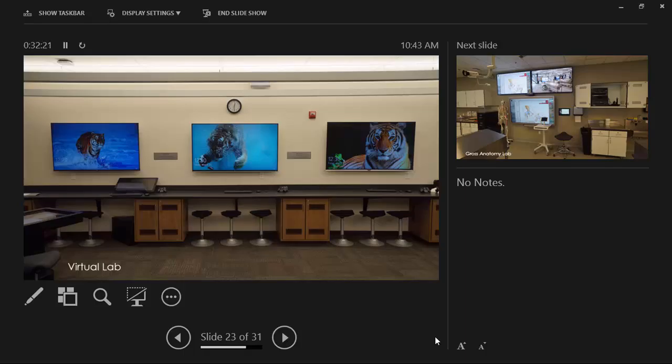Make sure you check in with Anatomage. There's a very specific, I don't know why. They're a DisplayPort output, right, but there's a very specific scaler, I guess, to take it from DisplayPort to HDMI. Without this particular model, I couldn't get it to work. I tried all kinds of Extron stuff that I have sitting around, which seems to work on everything else, and it wouldn't do a thing with these. But they recommended this one device, I don't know why it's that one thing, and they work great. So check in with Anatomage for sure, or I can get it for you if you let me know.